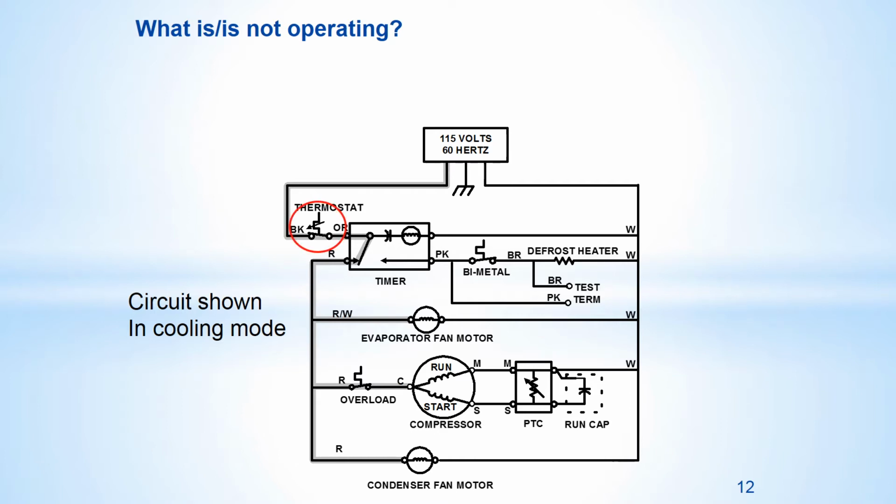It could be the thermostat, timer contact. The timer could be stuck in defrost. Or it could even be the power supply or a connection from the power supply.